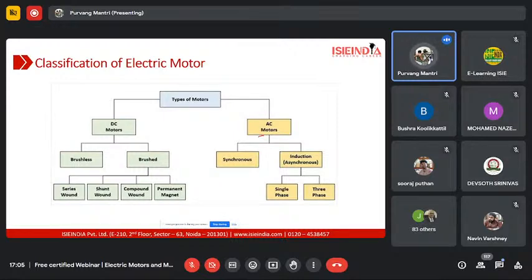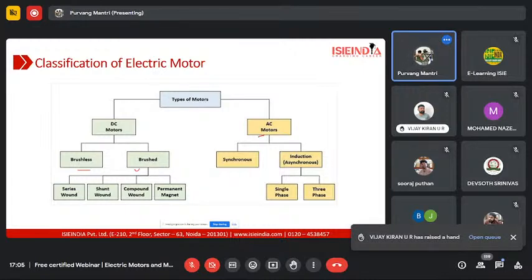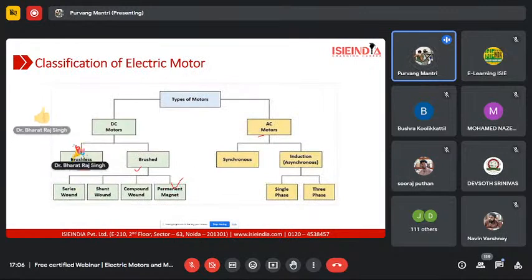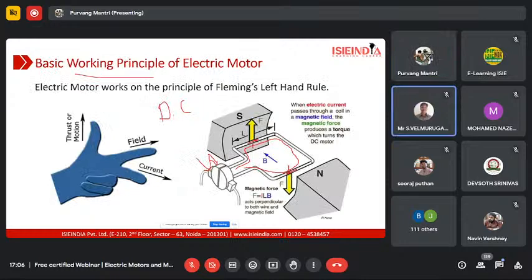First and foremost, we have the brushless type. Everyone is aware of the BLDC motor, and we are going to look deeper into it. Simultaneously, we might have learned about the brushed DC motor. The example that we looked at in this slide is actually a type of brushed DC motor. This is the basic working principle of a brushed DC motor, the one with a permanent magnet. There are other types of brushed DC motor in which, instead of using a permanent magnet, they use windings for the stator and rotor. In the basic example of a brushed DC motor which uses permanent magnets,